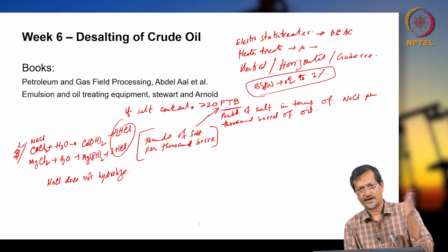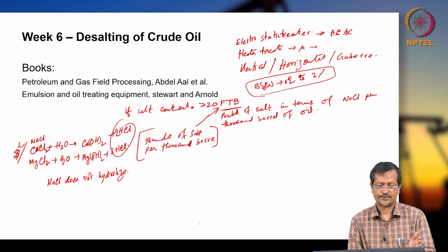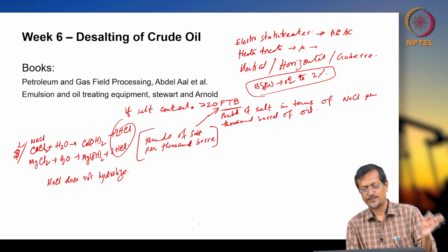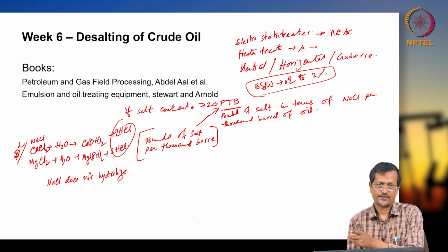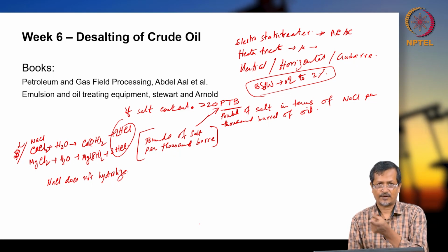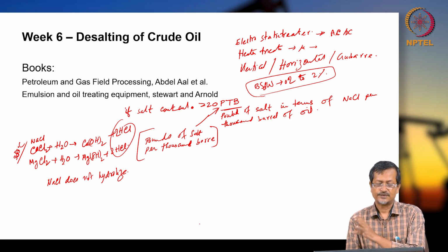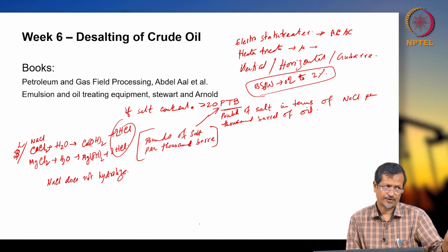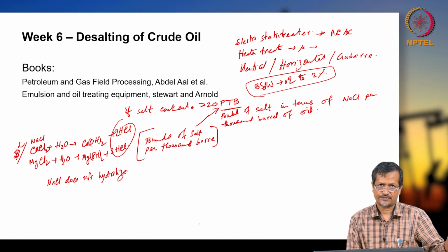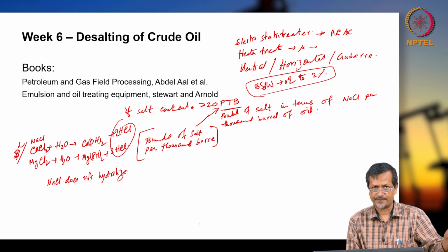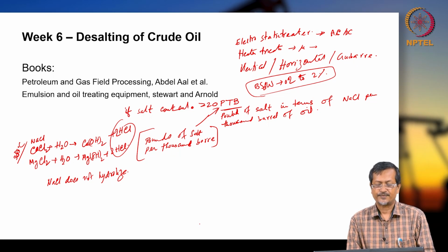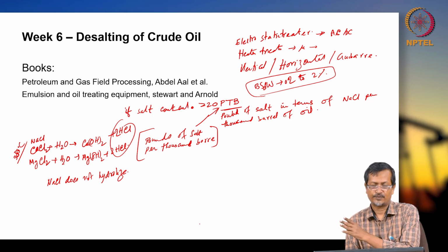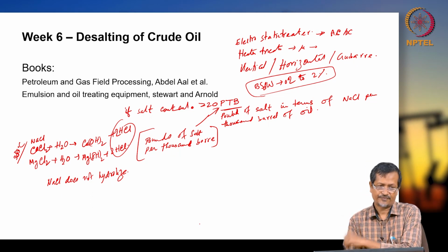But if you are having very high amount of PTB, so in that case, the surface production operation people should be separating, then they will be transferring to your customer in refineries. Okay, refinery, they will have also desalting equipment. So, this desalting equipment can be placed in refinery or in surface separator operation, where on the surface the upstream people will be separating. But in many cases, upstream people will be doing this work, and next level, final level will be done by your refinery people.